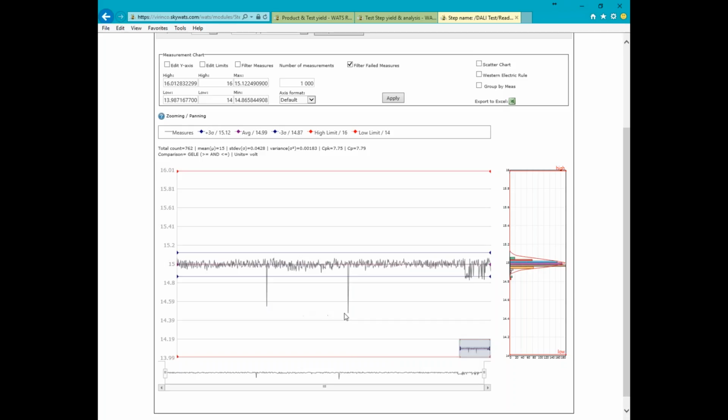These are a potential quality risk, but because the limits are so wide, they are not being picked up and failed by the system. Also at the bottom here, at the end here, you will see there are some irregularities in the data. We calculate the ±3 deviations, so we show you where we would have placed the limits if this is your data. These are the recommended settings, and these are clearly outside of this.